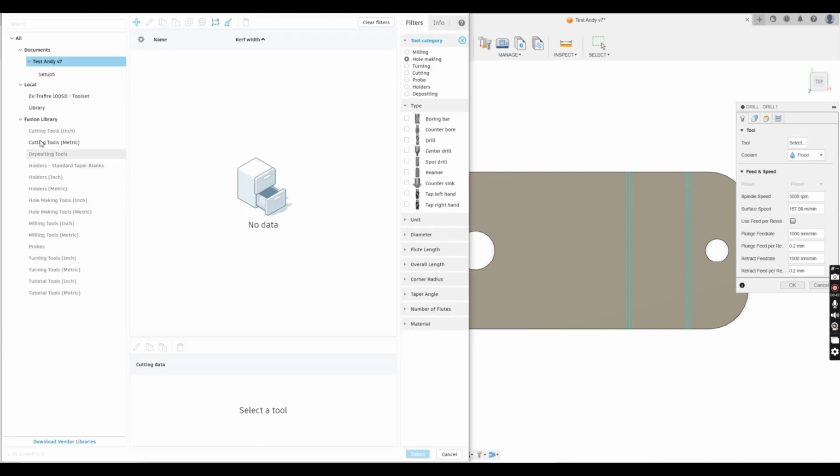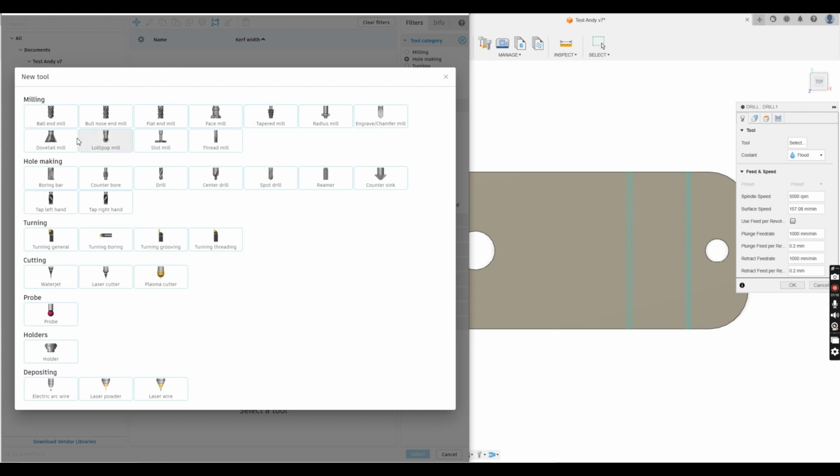You can build out your tool library similarly to how the Plasma tool library is built, by adding in tools. We can add in tools by clicking our button up here. But before we add tools, we want to make sure we're in the correct tool set. For example, this tool set here is set to this customer's Plasma. So I'm going to build a tool set inside this, so he's got all his tools for Plasma and drill all in one area. Once this is selected, this is our tool library folder, we can then hit the plus button here and we've got a multiple amount of different things we can add.